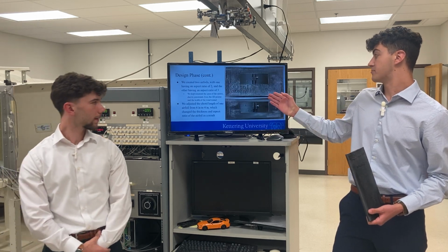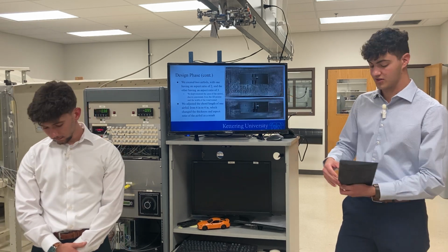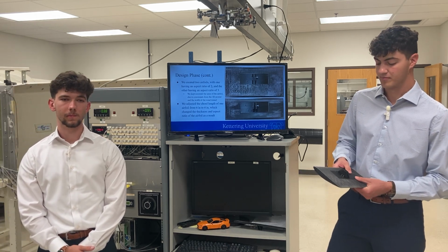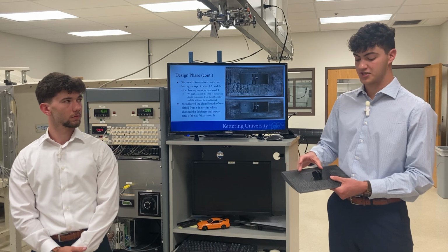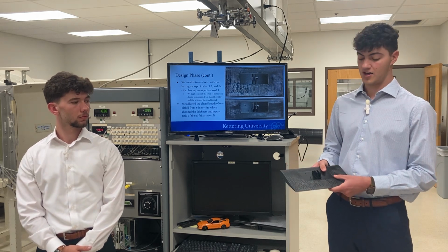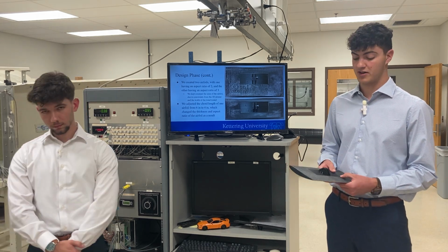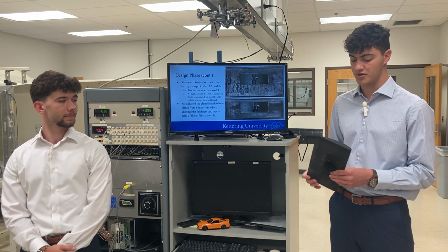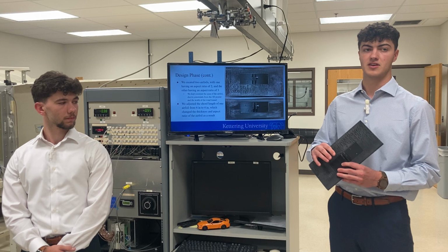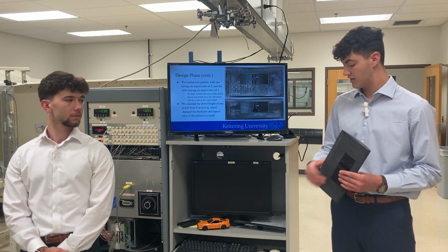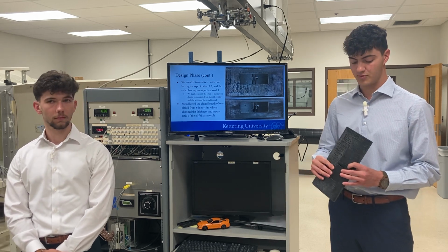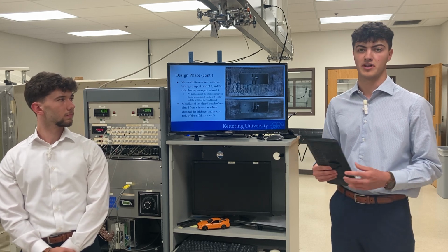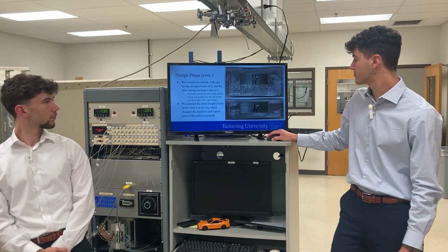And then this picture is basically to show the access panels on the bottoms of both airfoils. Although they are the exact same dimensions in terms of length and width, we did have to design 2 separate access panels for both due to the change in thickness. Because if we were to use the same access panel from the smaller aspect ratio on the larger aspect ratio, we would have had more parts sticking out and created a second stagnation point along our air draft.